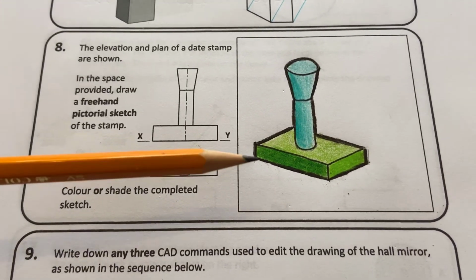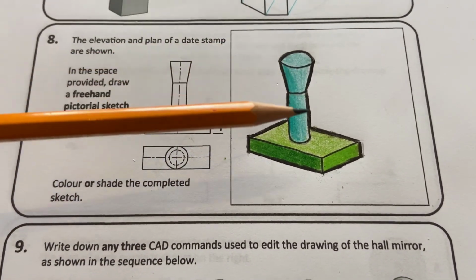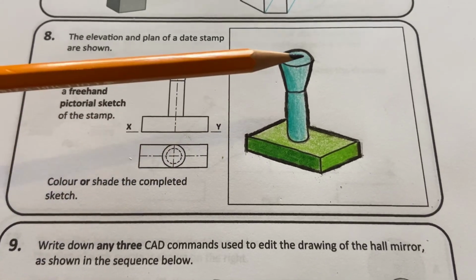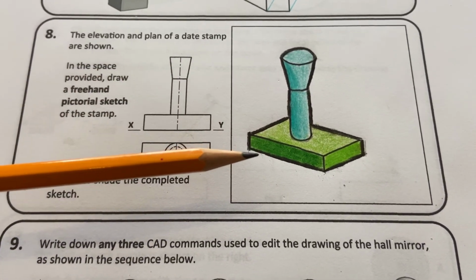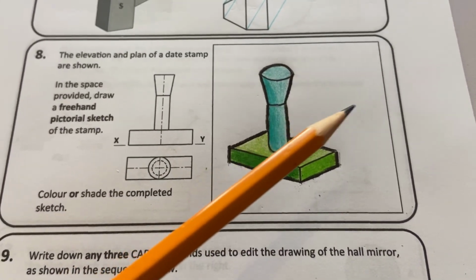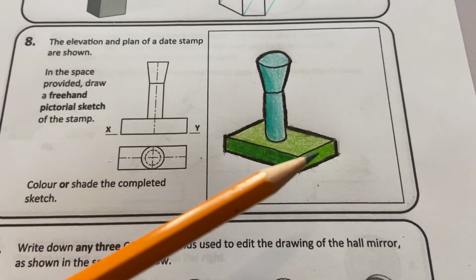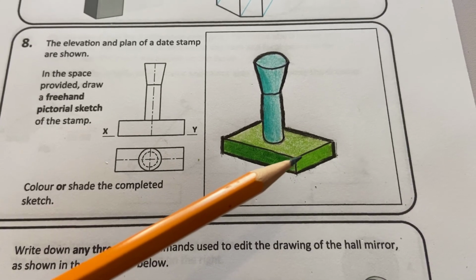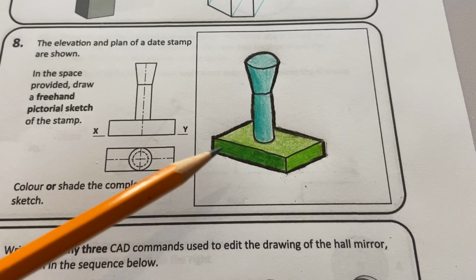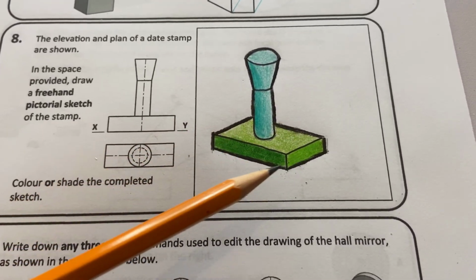So when applying shade to the drawing, first of all start by just going around the perimeter with a heavy black colouring pencil, as that just separates the drawing from the sheet and makes it stand out that little bit better. Again, assume your direction of light, and I've assumed that the light is coming in here from the top, so this top surface is getting lit up. This surface here will be lit up, so it's a lighter colour, and then this surface will be in shade, so it's a darker colour.